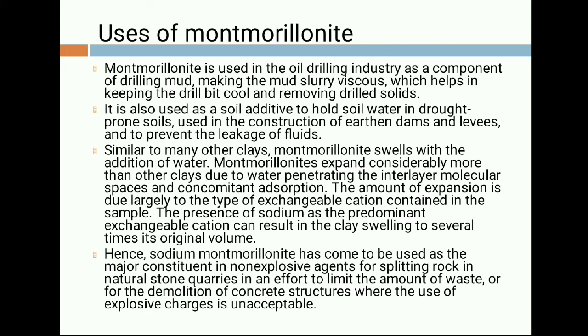Similar to many other clays, Montmorillonite swells with the addition of water. Montmorillonite expands considerably more than other clays due to water penetrating the interlayer molecular spaces and concomitant absorption of water. The amount of expansion is due largely to the type of exchangeable cation contained in the sample. As we have discussed, magnesium is replacing the alumina sheet. So based on what kind of ions are replacing the alumina sheet can give you different kinds of CEC, that is your cation exchange capacity.